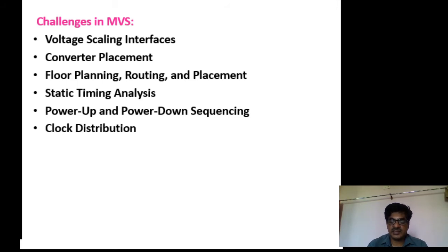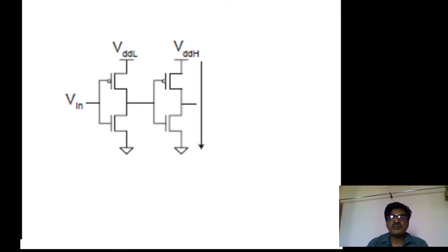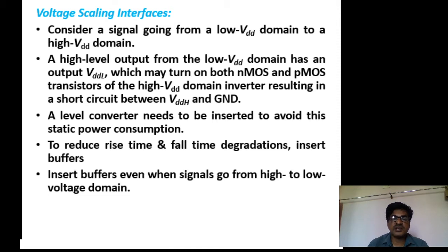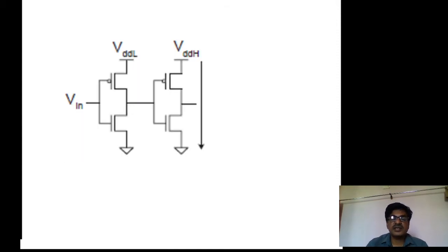What is the interfacing? Interfacing means providing a connection from one circuit to another circuit in general. But here the problem is, since the different subsystems work at different power supplies, their voltage ranges for logical 1 and logical 0 are different. So if they are in the acceptable range from one voltage domain to another voltage domain, there is no problem at the end result. But if they are not in the acceptable range, you can get error results at the end.